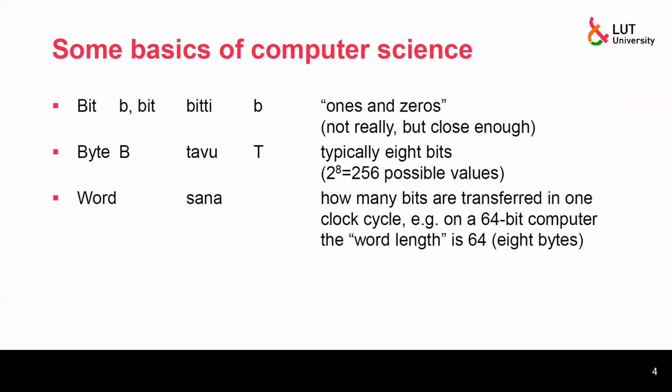I should have checked, but something like 4.8 volts is 1, and 0 volts is 0, and values slightly above or below are accepted, so there is a tolerance zone, and then there is a forbidden zone. If there's a voltage value somewhere in the middle, it's undecided which one it is. But there are other alternatives. If you have seen a CD, a compact disc, the storage uses a slightly different system. There's a different kind of reflective surface when bits swap from one to the other.